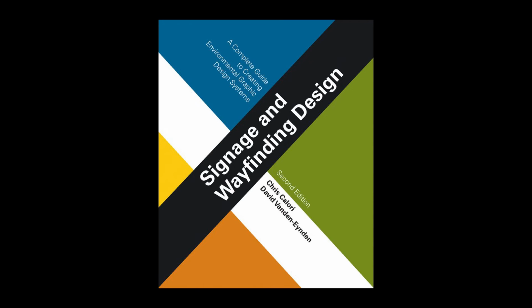A completely colorless, low iron content glass sheet is also available, but at greater expense. Additionally, glass sheet is available in a wide variety of colors, levels of transparency or opacity, and surface textures, typically from specialized art glass suppliers. Glass sheet is very hard and scratch resistant, but with a great enough impact it will shatter or chip. For this reason, glass is often tempered or laminated or both.